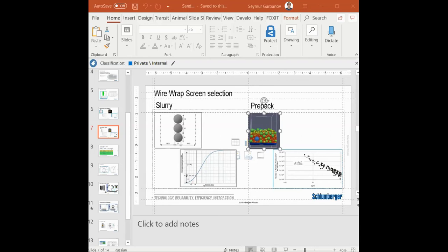The important thing is you need to analyze case by case. Maybe you have sand, but it's manageable. So there is no excessive amount of sand. There is an amount which is less than, let's say, 1,000 pounds per month. That's a really small amount, so you could live with that, just manage it at the surface. But if you have excessive sand production, excessive meaning you're producing a couple thousand, then definitely in that case you have to think about the erosion risks, and you have to think about what to do to improve your well life.